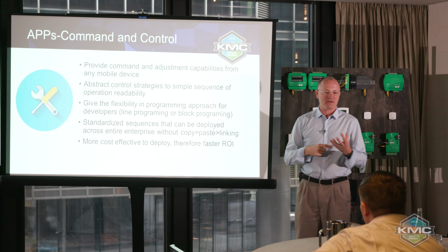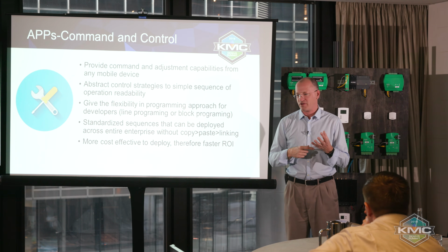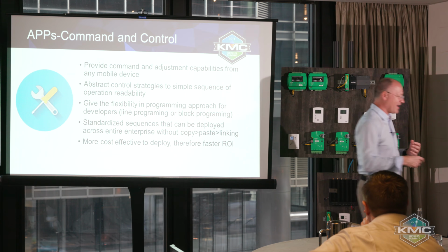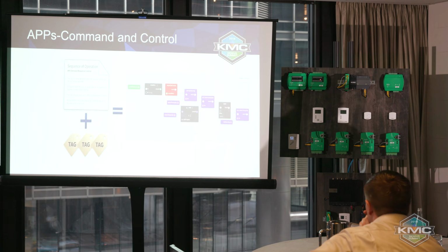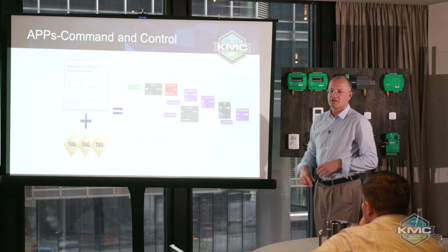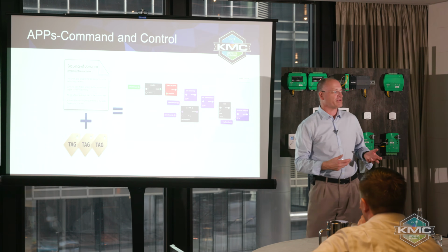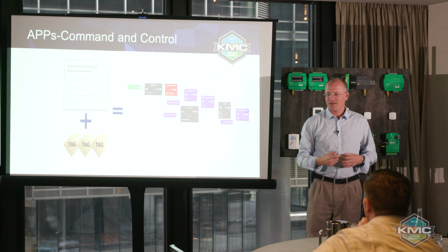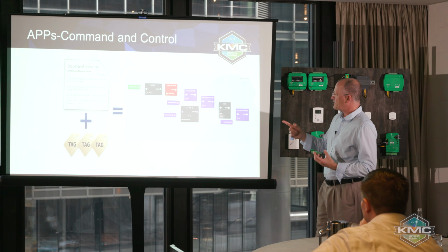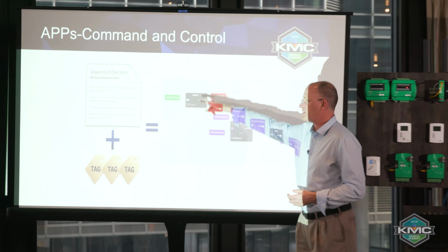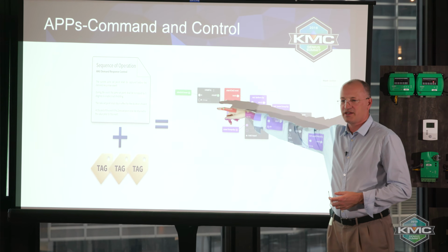So imagine being able to create one control strategy for, let's say, set point reset, and then have it automatically bind to as many VAVs or as many rooftops that need the set point reset algorithm applied to them. So, to give you a live example, this is maybe the blocks that go into creating the routine.